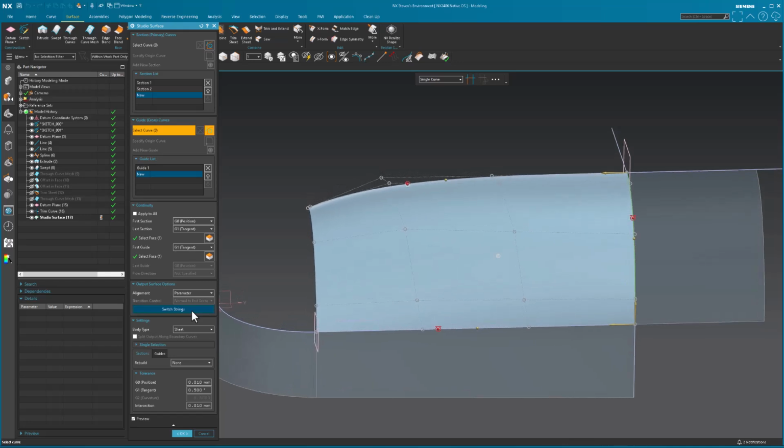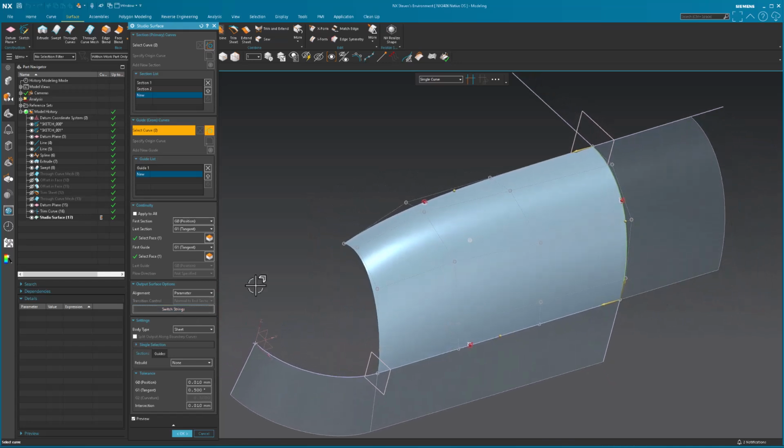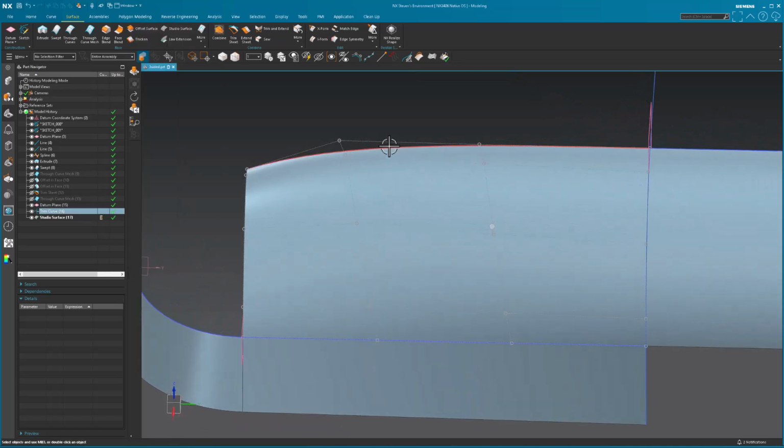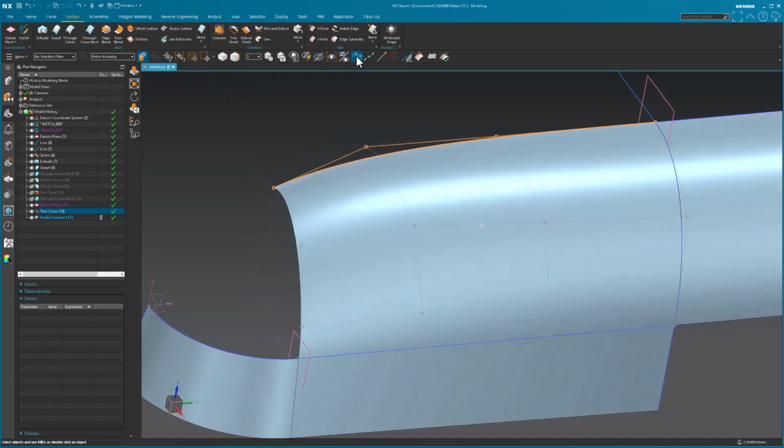The reason why is because this string is now driving the math of the surface, the primary string. So by using this as a primary, and this as a cross string, I get an even more simple, clean surface. Okay? And that makes me happy. Now, if I look at the control polygon of this once again, you'll see they align perfectly.